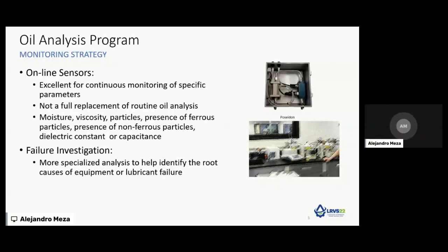They cannot replace a good quality laboratory oil analysis. But they are useful to detect when something is not going normally. There are more precise and more sensitive sensors than others, but selecting the right sensor for the application may report to us immediately that something is not running normally. While the sensor may not be able to tell exactly what is happening, it alerts us, sends the information to a PLC, to our cell phone, or computer, and we can immediately take a sample and run oil analysis.